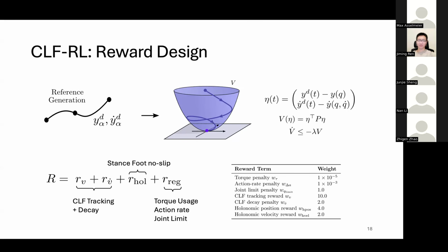And then there was one other comment I'll just say with choosing the Y. What I've done in more recent works is I've chosen my Y to be both the joint positions and velocities and the end effector positions and velocities. This doesn't hold as well with the classic CLF theory, where you would really have to be actuating on output. So your error needs to be on actuated outputs, because in this case, we'd be kind of double dipping. But for RL, practically, I think this helps. So the choice of Y is up to you as designer.